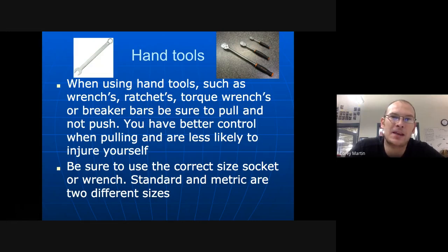So if you're trying to make an adjustment on an engine while it's running, or you're trying to diagnose a problem on an engine while it's running, which does happen quite often, you're going to have your hands and face around all these moving components. So let's say that you have a bolt that's really, really tight. You're on the tool, you're on the fastener, and you're trying to leverage your body against the force of that bolt and break it loose.